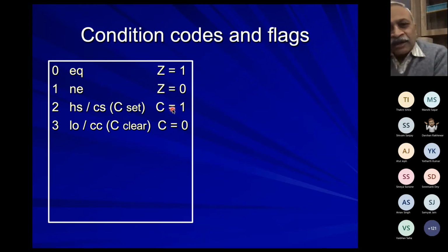So can you see that 2's complement, suppose x is a number, 2's complement of x is nothing but 2 raised to power n minus x. And when you add these two, you get 2 raised to power n. And 2 raised to power n would show up as a final carry and all zeros for the sum.